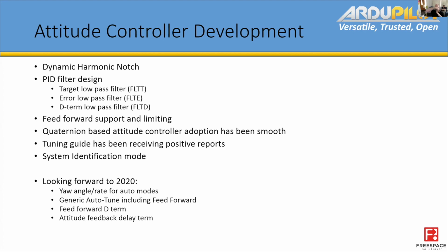At the moment, initially you're at zero, and when you come up, you get this gap between where you want to be and where you are. The controllers then move that up to match during that maneuver. And then when you flatten off, you get an overshoot because there's a delay in its reaction again.